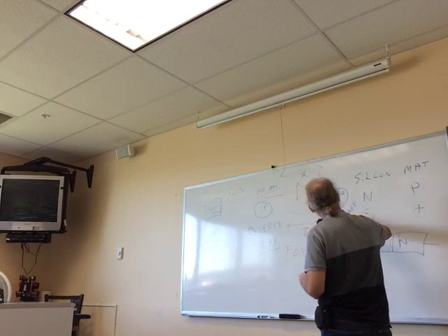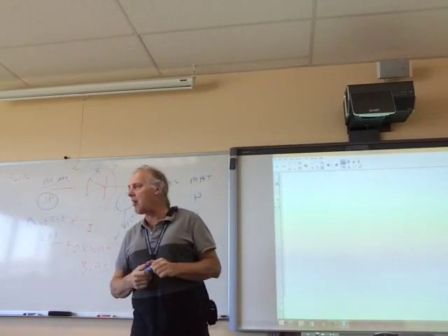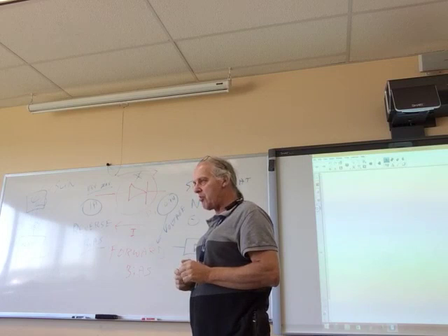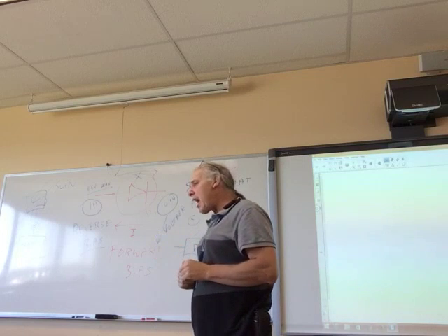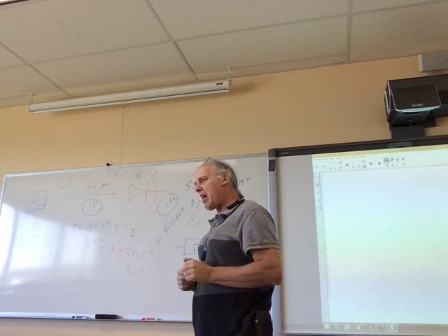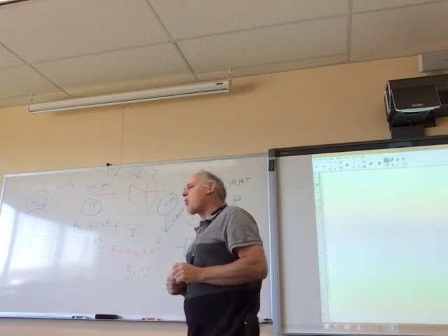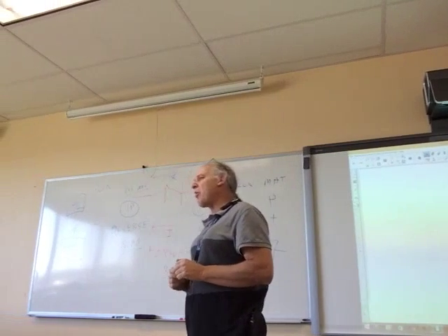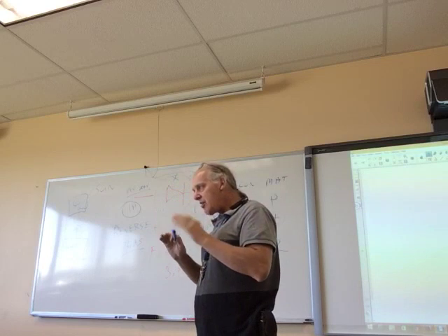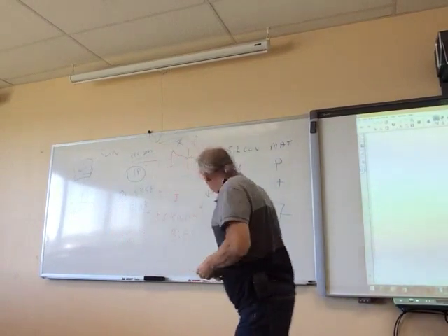And if you don't, when you do your calculations on your power supply, they will be wrong. We're going to do a lab today that actually shows that 0.7 volts. Now, germanium diodes are lower, and we still use some germanium diodes and some diodes called pin diodes because their forward voltage is about 0.3 volts. So it's much lower.